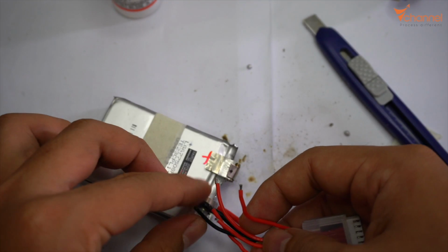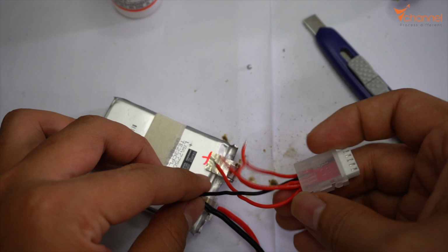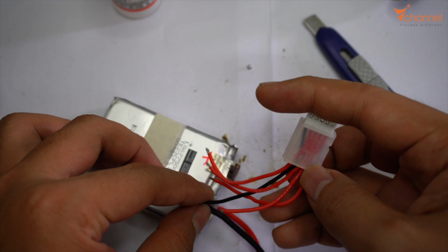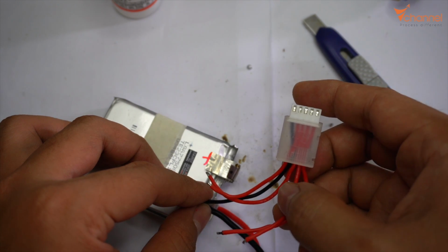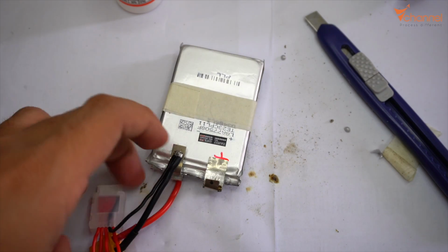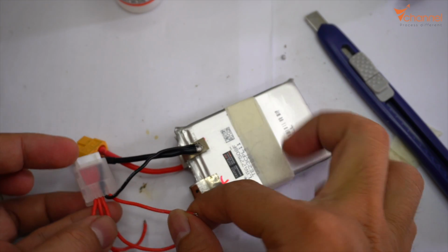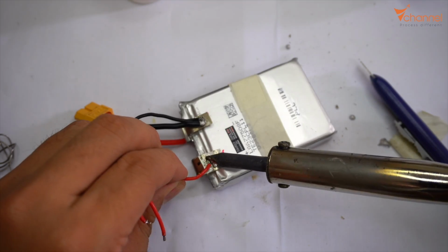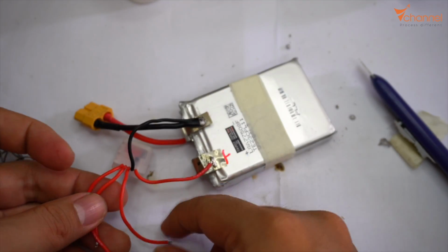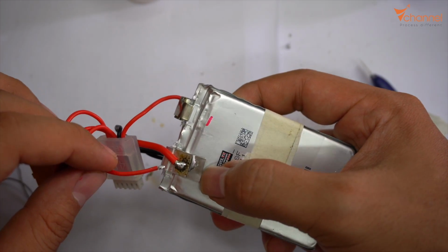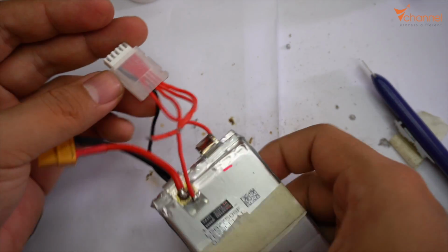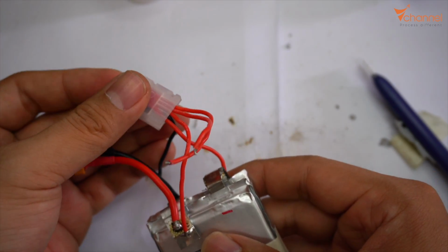In that case, it will charge each cell separately and monitor the voltage of each cell to keep the voltage the same on every cell, positive plate to negative plate. First red to the first cell positive plate, next second white to the positive plate of the second cell, and so on. Okay, perfect. We have the total jack and balance jack here.